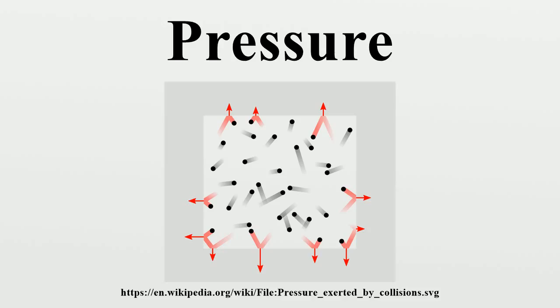Where space is limited, such as on pressure gauges, nameplates, graph labels, and table headings, the use of a modifier in parentheses, such as kPa(g) or kPa(a), is permitted. In non-SI technical work, a gauge pressure of 32 psi is sometimes written as 32 psig, and an absolute pressure as 32 psia. Though the other methods explained above that avoid attaching characters to the unit of pressure are preferred.